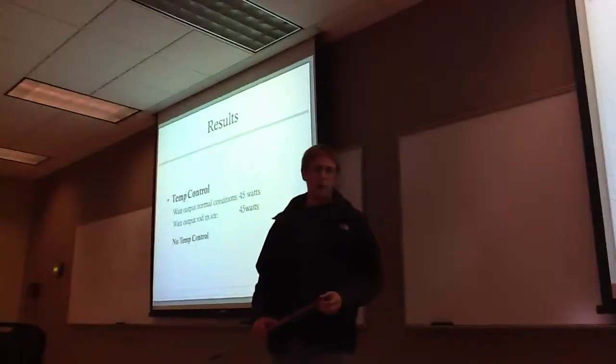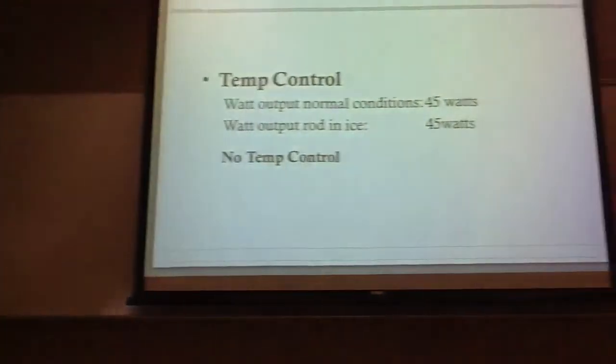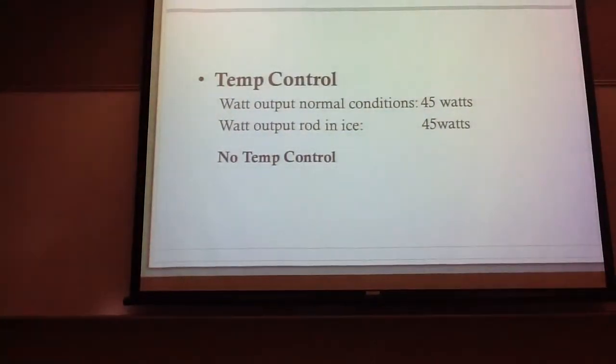We measured the watts going into the soldering iron under normal conditions, and then we stuck the soldering iron in a cup of ice, and the amount of watts going into it didn't change, so we concluded that there was no temperature control system in the soldering iron.